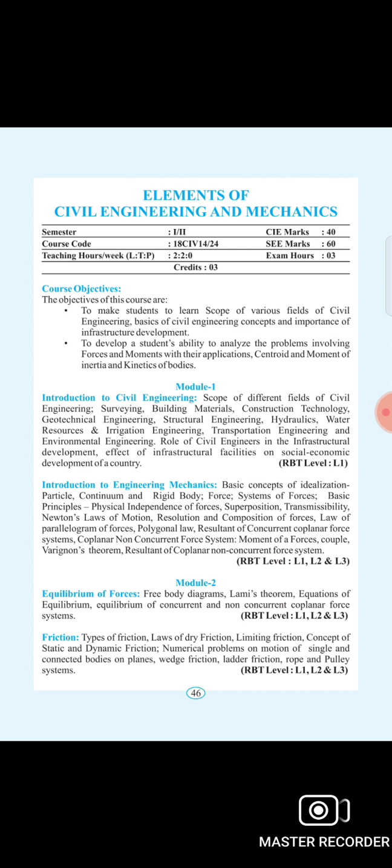The body may have a number of forces applied, such as supports, reactions, or some other force. The analysis of the equilibrium condition of the body is to determine the reactions with the adjacent bodies in contact. We call that equilibrium of forces. The principles involved are the three equilibrium equations in the horizontal direction, the vertical direction, and the moment. Moment is force into perpendicular distance. So that is sigma H, sigma V and sigma M, considered about one particular point to find the equilibrium condition.